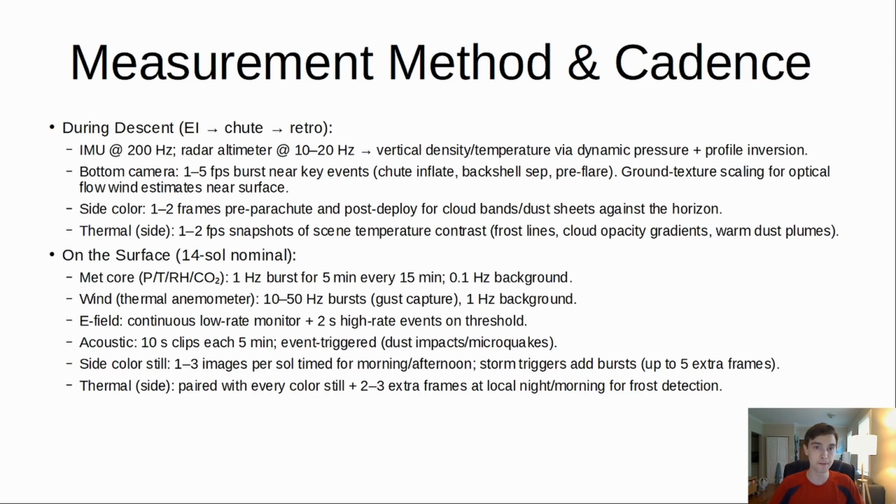Got a seltzer. So, the measurement method and cadence. Obviously, we'll be recording during descent. Our IMU will be recording, with probably a radar altimeter, and then vertical density and temperature via dynamic pressure and profile inversion.